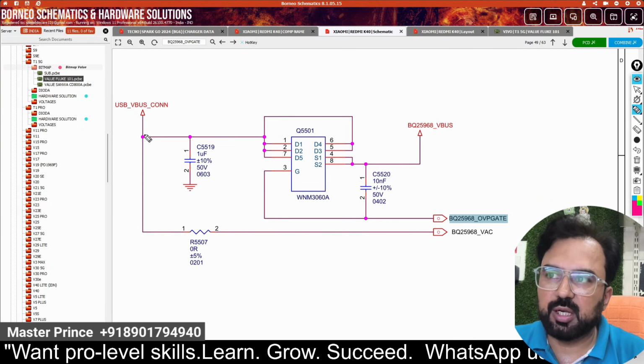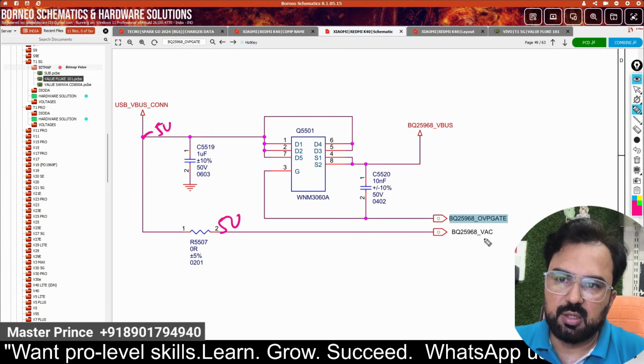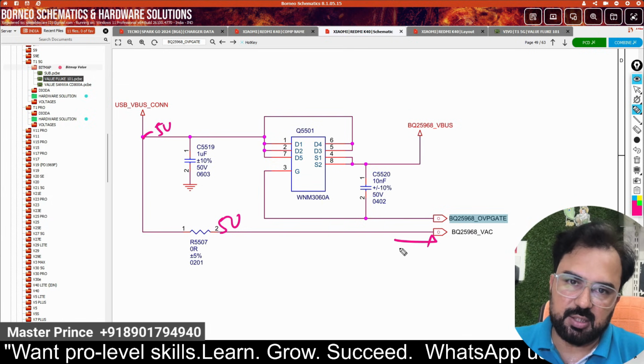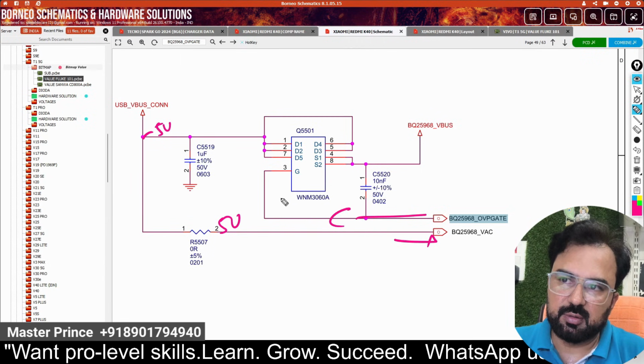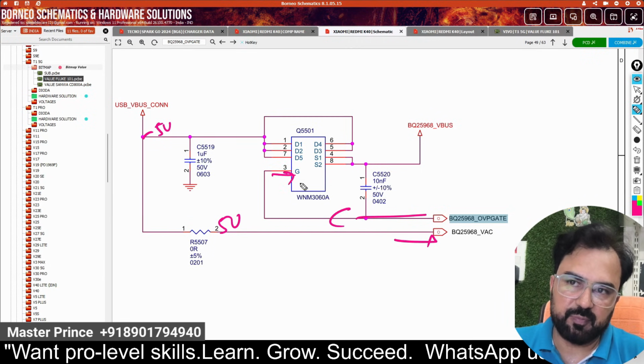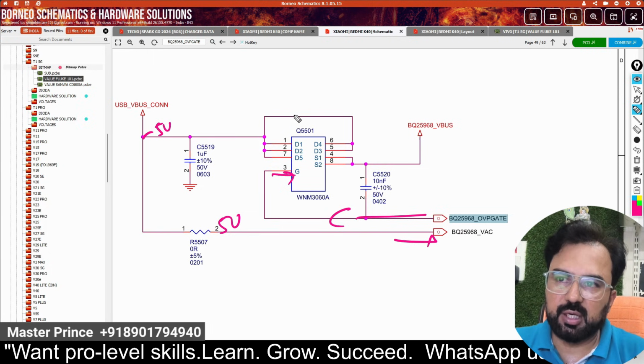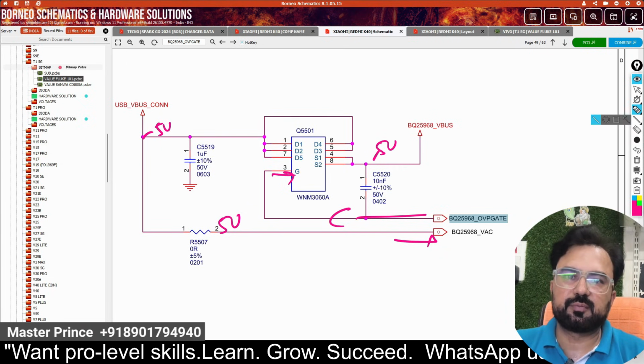So when you connect a charger, 5 volt goes through this resistance to the BQ IC. When BQ senses the charger is connected, the adapter is connected, it sends an enable signal to the gate to enable this MOSFET. After enabling, this 5 volt enters here. Clear?